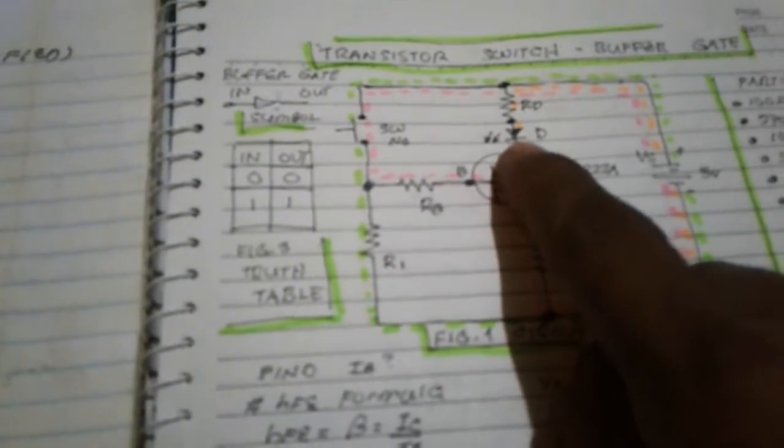Using the transistor formula here, we get IE is equal to IC plus IB. We know IC, that is 0.02. The collector current is the same as the diode current or resistor current here, which is 0.02 ampere, given in the data sheet of the LED. Plus our IB here. IB is now 0.0002 ampere. Finding R1.